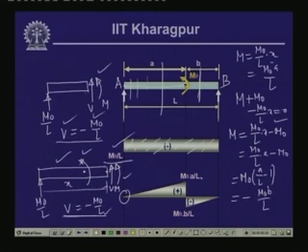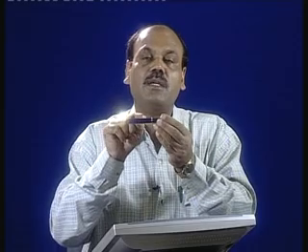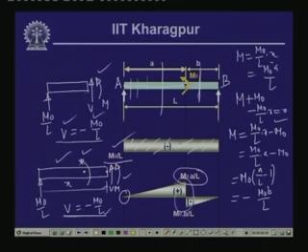So, here you see on the left hand side we had a bending moment of M0 A by L. Now, in the beam where we have the concentrated moment, on the left hand side we had a value of positive M0 A by L, and immediately next to that point of the concentrated bending moment we have the bending moment which is equal to negative M0 B by L. So, there is a sudden jump in the bending moment from the left to the right where we have a concentrated moment. So, this is what is reflected in this particular diagram. At this point here we have M0 A by L and here we have M0 B by L, and again at x equal to L, if we substitute here you get M0 minus M0 as 0.